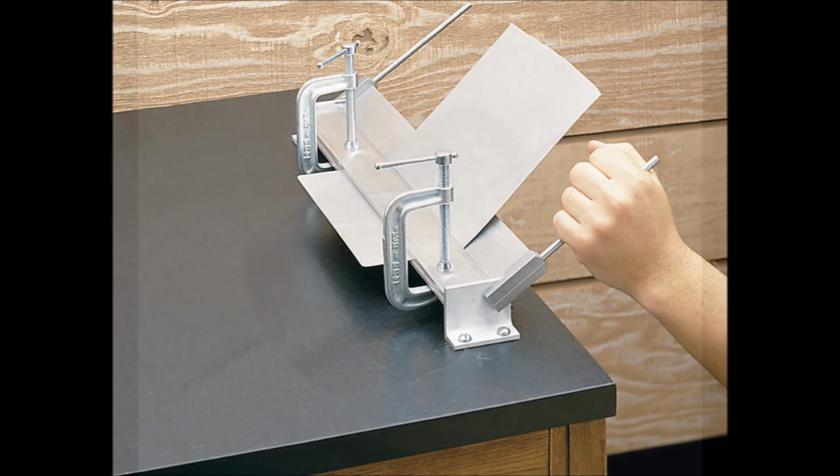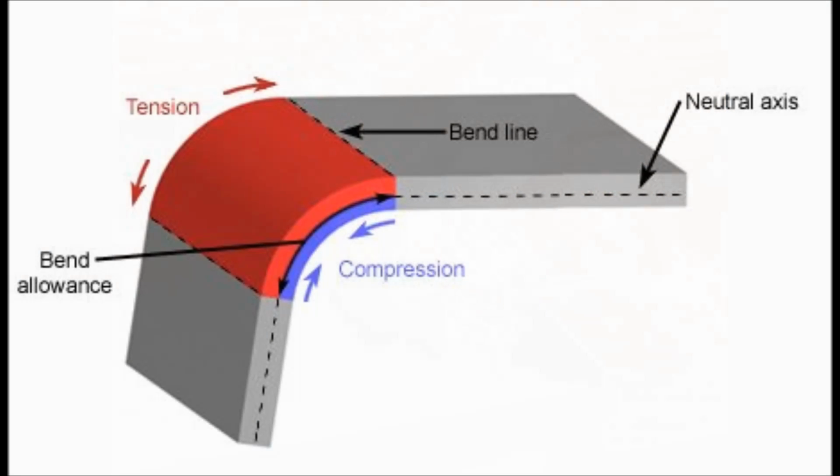Pay careful attention to bending the material. Because the magnetic properties are highly dependent on the size and shape of the metal crystals, any manipulation such as bending or high heating which alters the crystal size and shape will adversely affect the ability of magnetic field lines to travel through that area. Often bending is absolutely necessary. One can either accept some decreased performance or re-anneal the material after forming to achieve peak performance.